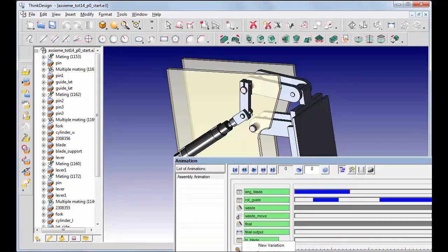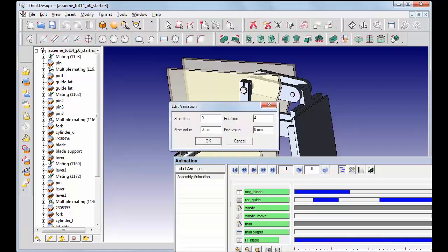Right-clicking on the box on the right of the new evolution, where we can define its variation, let's now choose New Variation in the context menu. This will enable us to define the behavior of the new evolution by assigning the chosen variable values through time. As soon as the blue area related to the variation of the chosen evolution is displayed, let us right-click on such area and choose Edit Variation, which will enable us to modify it.